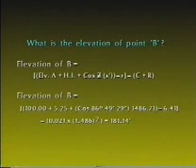Notice in this example the correction for curvature and refraction, about minus 0.05 feet, must be included. With this type of leveling, the balancing of forward and backward sightings, or simultaneous trigonometric leveling, will eliminate the need for correcting for curvature and refraction.